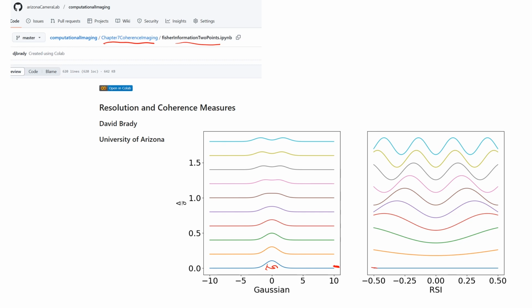On the right, we're seeing the output of the RSI. Now, if an RSI is pointing directly at a point source, looking at a plane wave, we can align it to cancel the plane wave on one of the arms, so we get 0 output on the arm of the RSI. Here we're assuming that the RSI points at the midpoint of the 2-point targets. So if the targets are exactly on top of each other, it's pointing directly at the target.